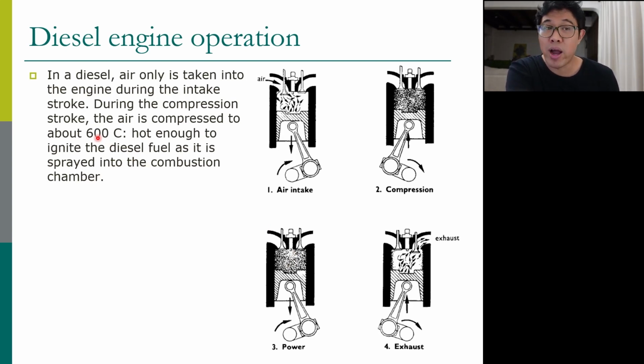That's why modern diesel engines compete, by increasing the pressure of the diesel fuel. If you can increase the pressure of diesel, you can spray the diesel such that it has very small droplets, and then it can burn very well, and you get more power. You get better fuel economy, a lot of things.